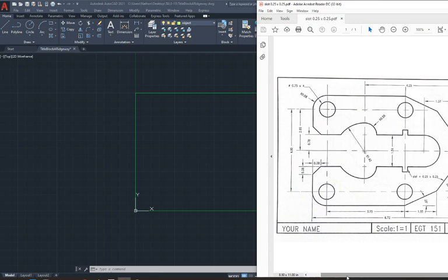Well, it is a good rule of thumb to look at all of the measurements that you have and start with the largest one. This is because the largest measurement might be larger than the title block that you're drawing inside of. You might realize, oh, my scaling factor needs to be higher, I can't fit inside of this title block. It'll also give you information on how to orient your drawing if it does fit inside your title block.